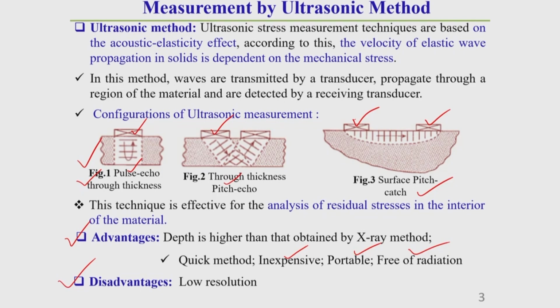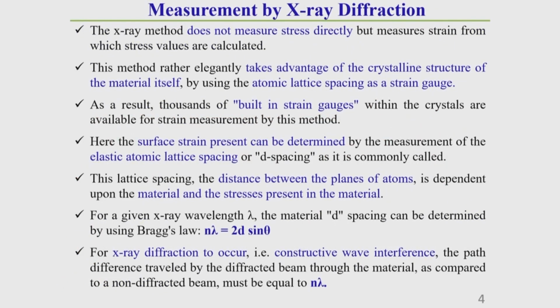Now, I will discuss other non-destructive residual stress measurement techniques, especially X-ray diffraction and neutron diffraction techniques. First of all I will discuss the X-ray diffraction method. The X-ray diffraction technique generally measures residual stress by measuring the strain. So, it is not measuring the stress directly, this you should keep in mind. First of all, it measures the strain through the lattice structure. From the strain measured in the lattice structure, we can predict how much residual stress is present in that specimen.